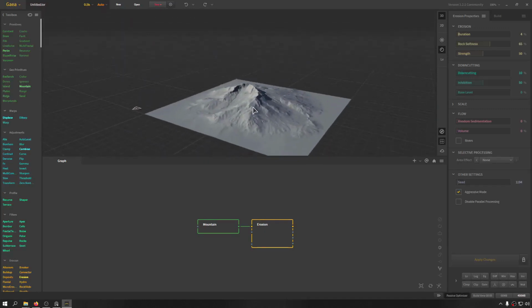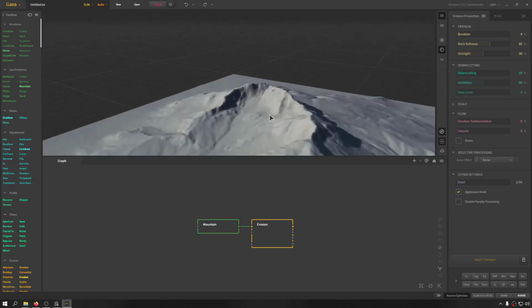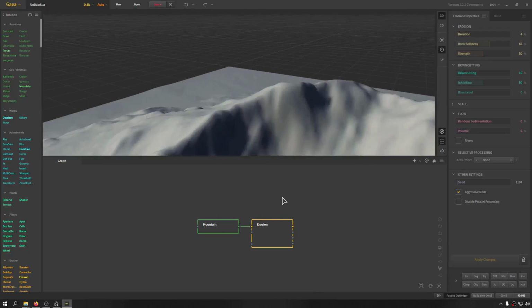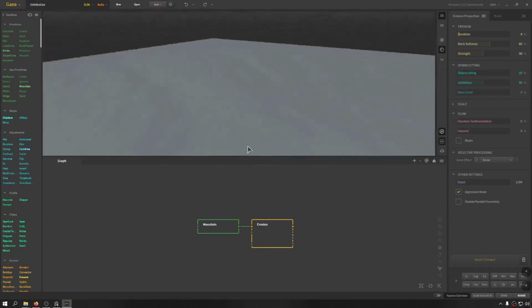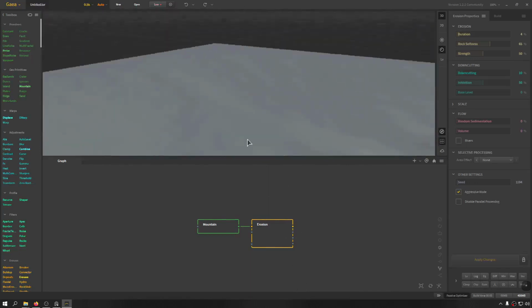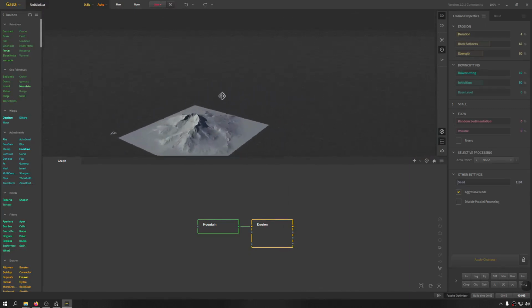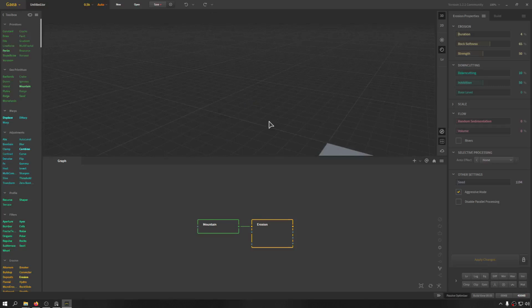And to zoom on the landscape, you either zoom with mouse or Alt click and mouse middle click hold, drag front and back to zoom out and in. And using Shift and middle click, you're able to pan around the terrain to see what it goes.